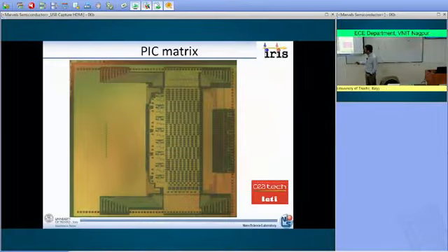Before bonding, here you see the gratings, the different gratings. So you need to have 4 gratings for the direction and 12 gratings for the add drop channels. Then here you see all the different microring, double microring resonator-based switchers. Here you see the demultiplexer, the AWG. Here you see the interleavers. In the output you have again the interleavers.